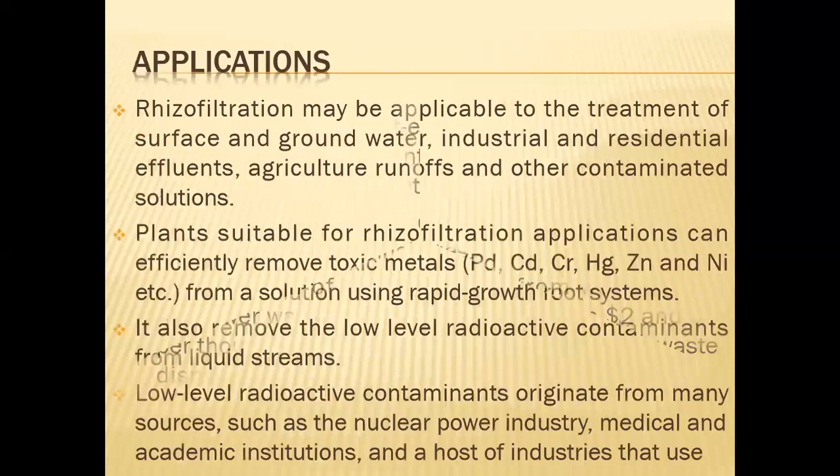Moving to the next slide, there are applications of the rhizofiltration technique. Rhizofiltration may be applicable to the treatment of surface and groundwater, industrial and residential effluents, agriculture runoffs, and other contaminated solutions. Plants suitable for rhizofiltration applications can efficiently remove toxic metals like lead, cadmium, chromium, mercury, zinc, and nickel, etc., from a solution using rapid growth root systems. It also removes low level radioactive contaminants from liquid streams.